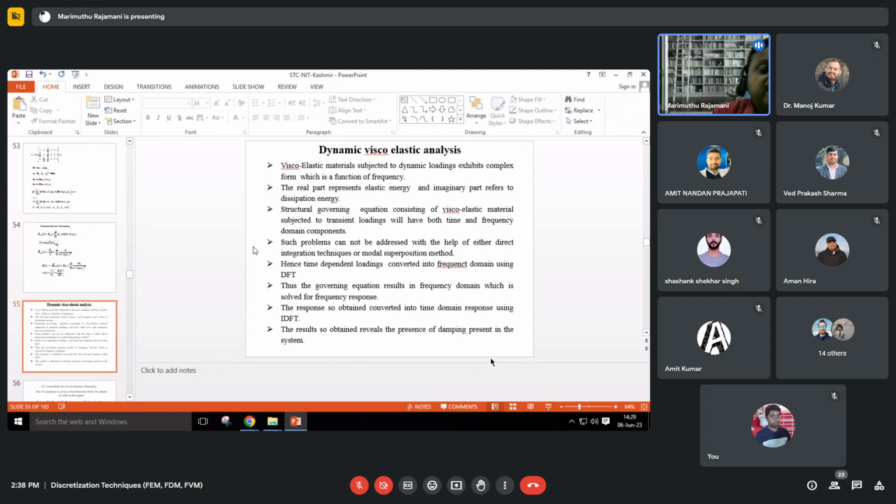actually it defines the shape of the field variable, how the field variable varies within the element. Shape function or interpolation function, both are the same. To explain, I will consider a simple bar element. A bar element has 2 degrees of freedom. It only deforms in the axial direction. So if you take an arbitrary element, you will have 2 displacements, that is u1 and u2. It is a 2 noded bar element.